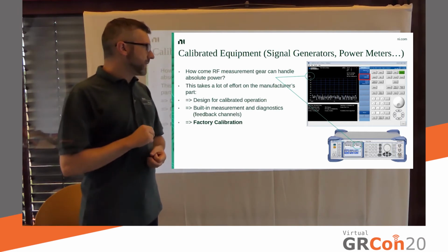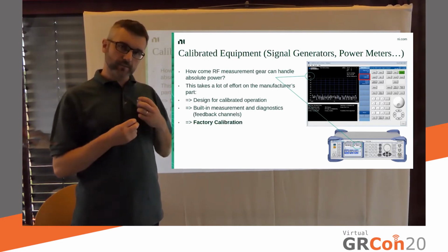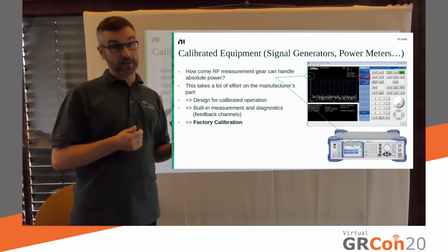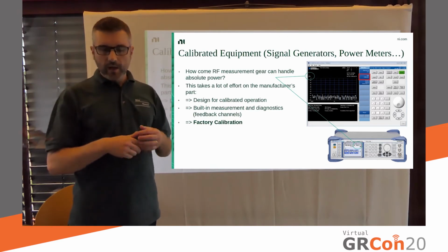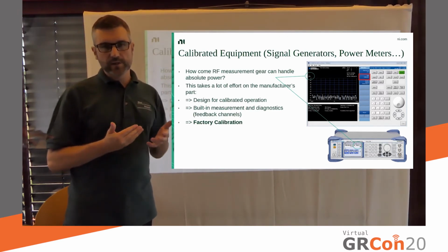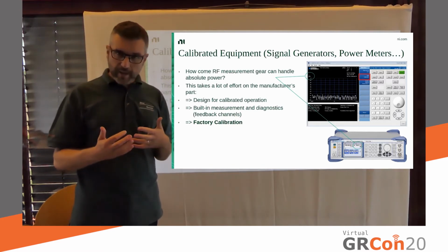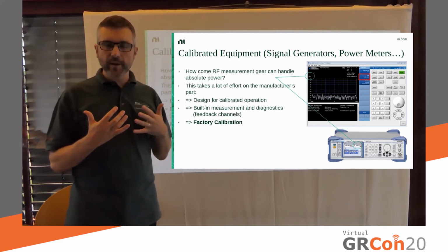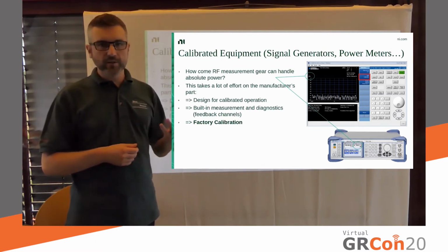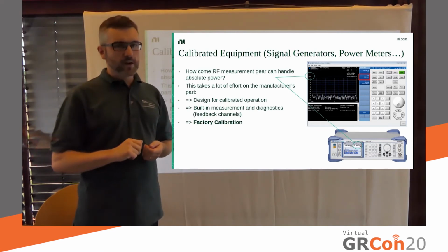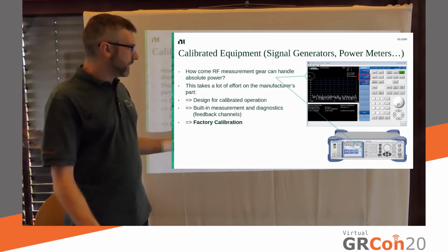So what's the problem? Well, first of all, professional measurement equipment is designed differently from an SDR, where this calibration information is one of the most important things, which is not true for SDR, where we think about low cost or size, weight, and power, stuff like that. So this is a big design criterion. And also the designers spend a lot more time thinking about exactly these relationships between power and how I can model that. They usually throw in a lot of sensors, temperature sensors, power sensors, that feed back information. So I can have some kind of algorithm running in the device that handles my 0 dBFS to x mapping. But most importantly, they do factory calibration. If you buy a new spectrum analyzer or something, it has a sticker on it that says calibration valid until, well, on my devices it'll say October 2008 or something like that. So factory calibration is a key piece of the puzzle.